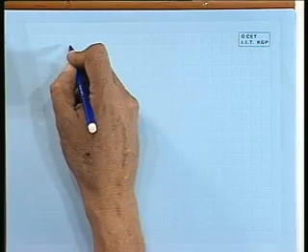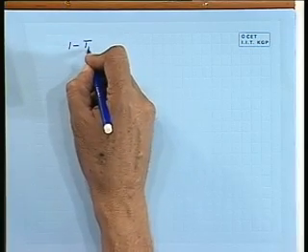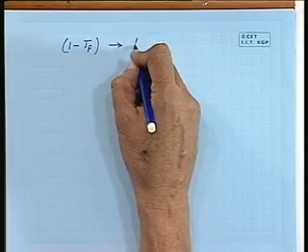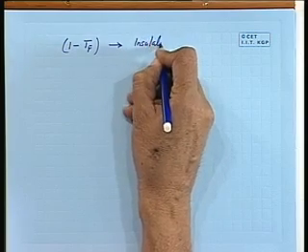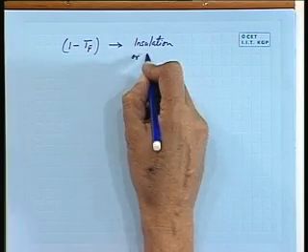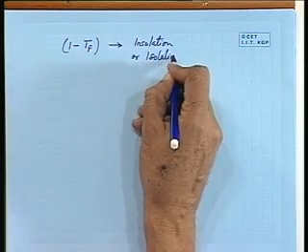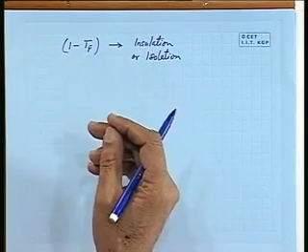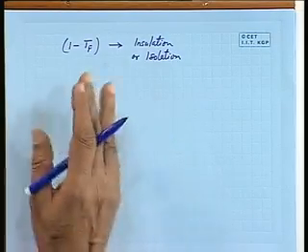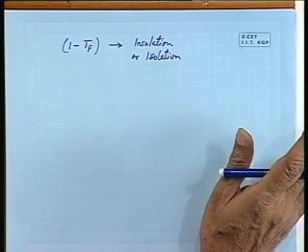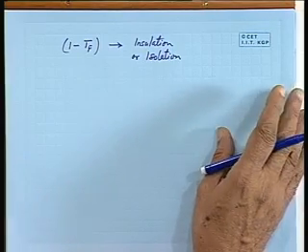And this being a ratio, the quantity 1 minus TF is normally used, and this term is known as insulation, or isolation. So, we do not say that 20% of the force is to be transmitted to the base, rather we will say that it should have an isolation of 80%.